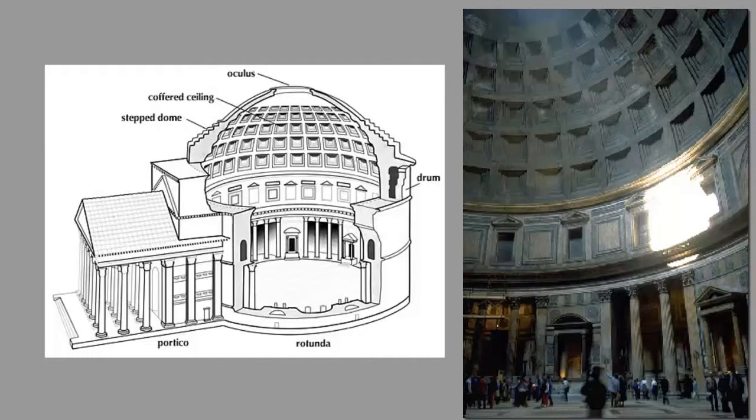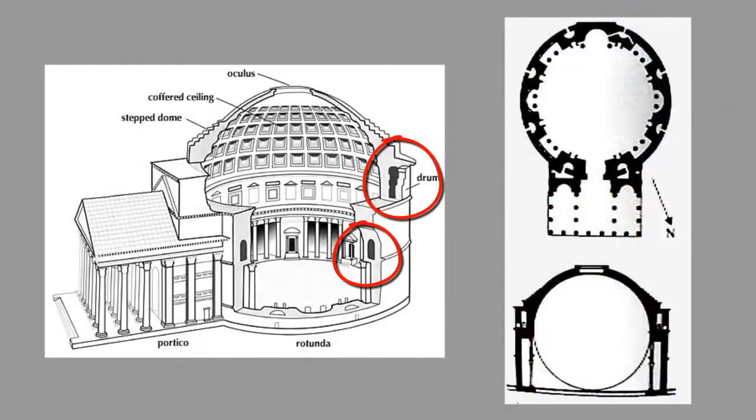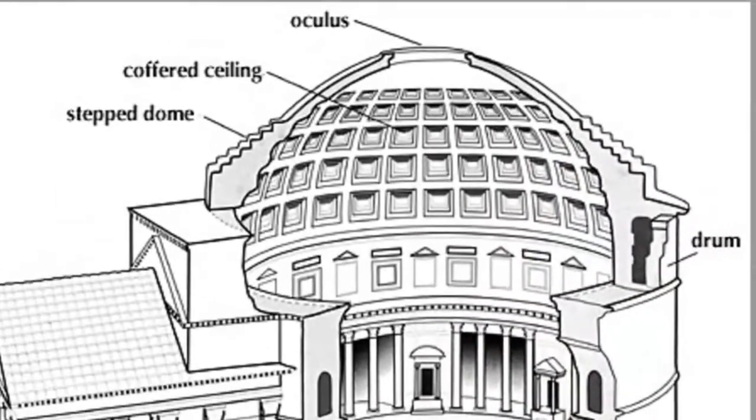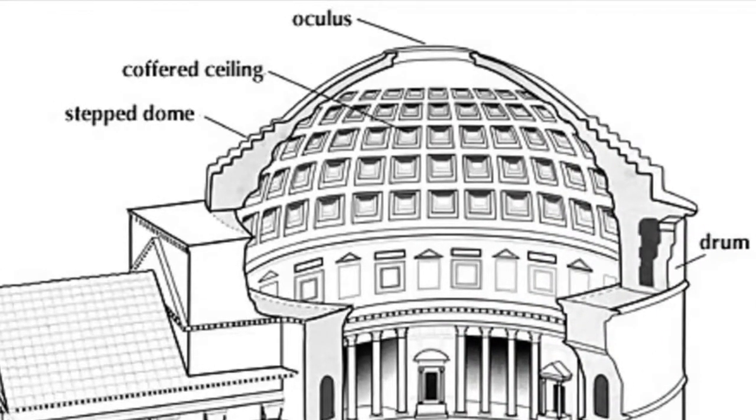The drum has a series of barrel vaults that run around the interior of it. And this dome is also stepped up, and the cement gets thinner and thinner as you get near the top, near the oculus on the very top of it. Now, they also changed the composition of the cement, and what I should mention is one of the things the Romans did is that they figured out certain kinds of sands, like sand from Pozzuoli, that's a volcanic sand, would slow the drying process down so that they could work the cement and mold coffers and things like that with a little bit more leisure.